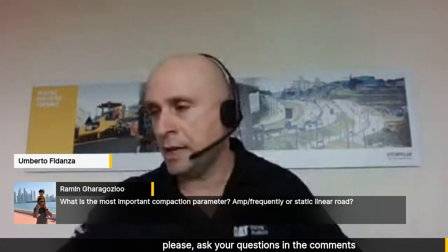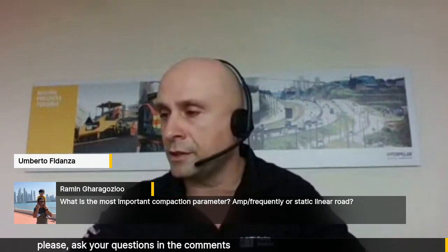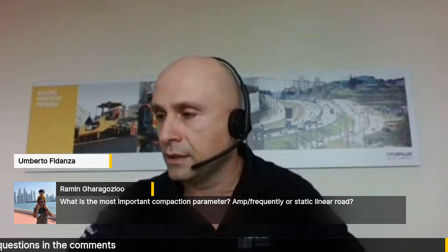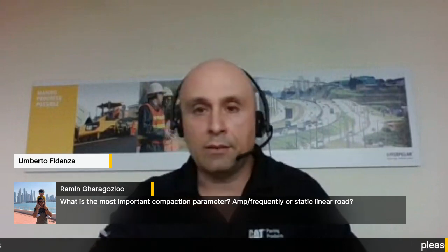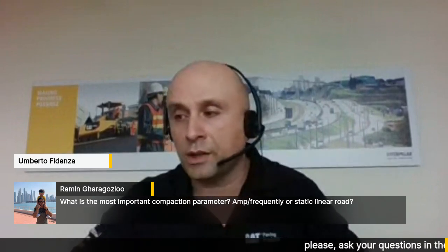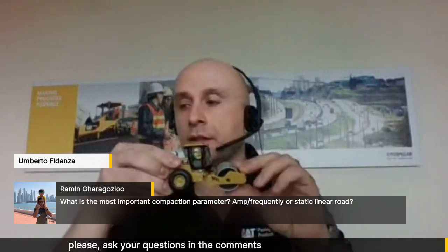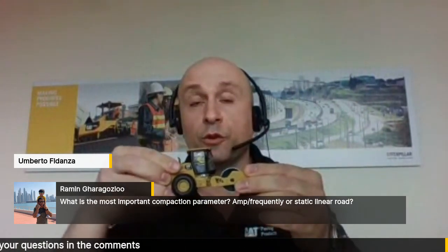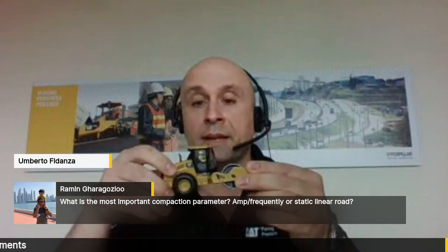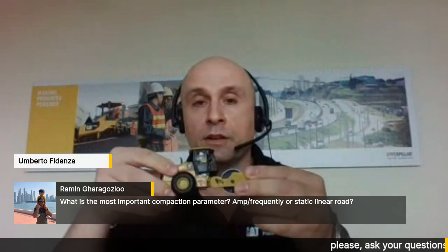Another question is about what is the most important compaction parameter: amplitude, frequency, or static linear load? I'll relate the answer to the four forces we mentioned in one of the first slides.